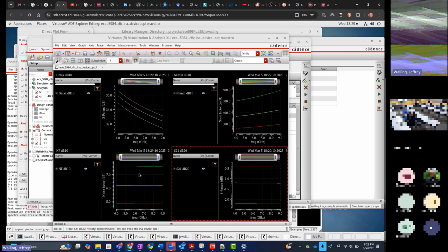All right, you can see, of course, the gain gets better at low temperature. That makes sense. What do we think, is the noise better at low temperature or high temperature? Low temperature, there's kT somewhere in there, right? So minus 40, quite a substantial difference, right? 0.27 versus 0.38. Yeah, pretty good. All right. Okay.